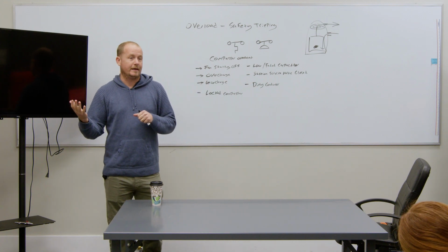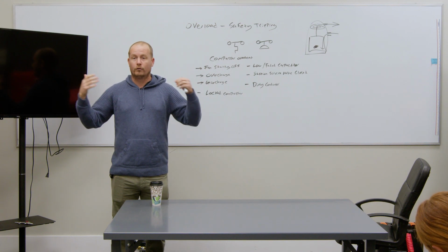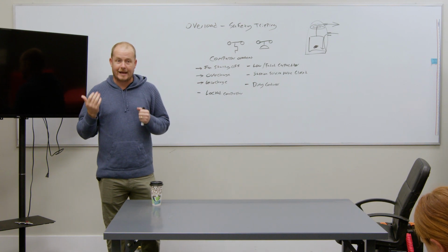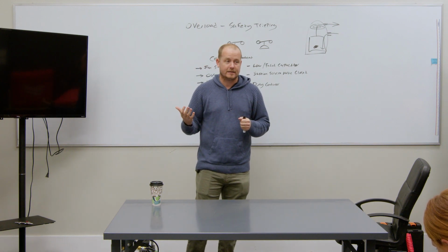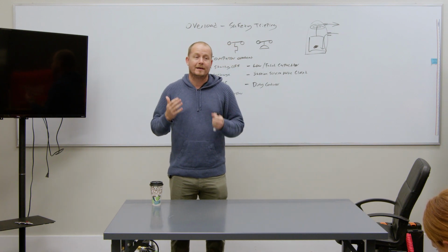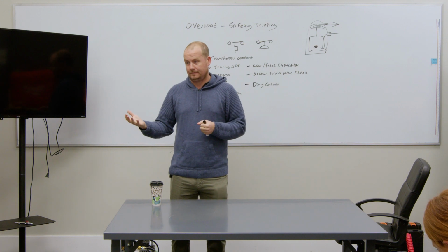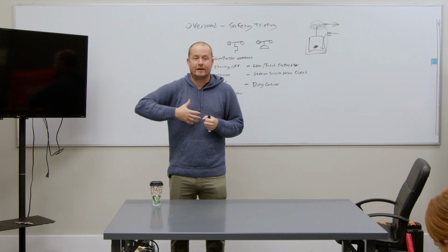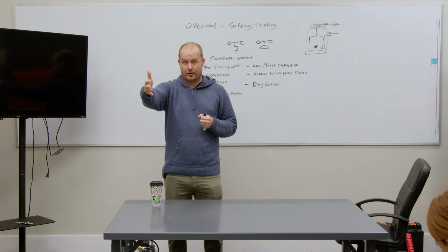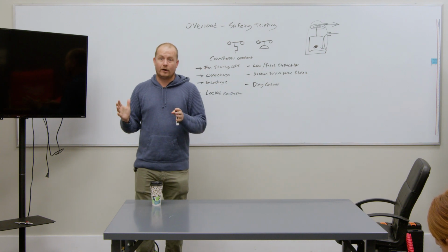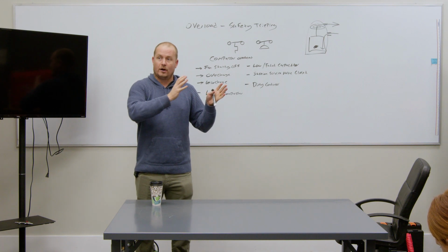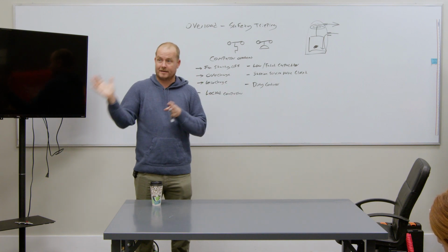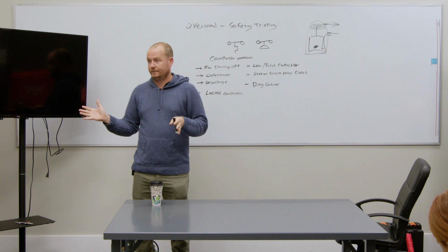Overcharge results in that compressor having to do too much work and being overloaded. You can actually have cases in refrigeration where systems come out of defrost and the compressor can overload because the suction pressure is too high. It's trying to do too much work. That would be too high of current. So we literally can overheat a compressor or overload a compressor because our suction pressure is too low or because it's too high. Either one.